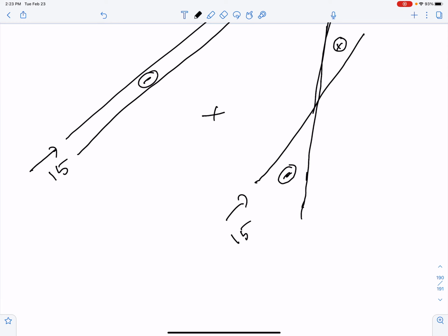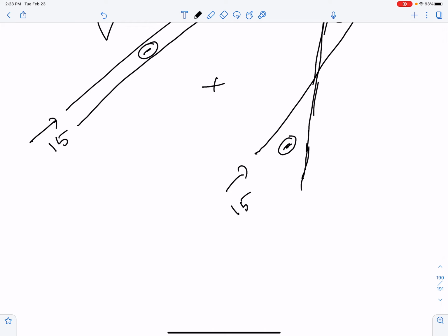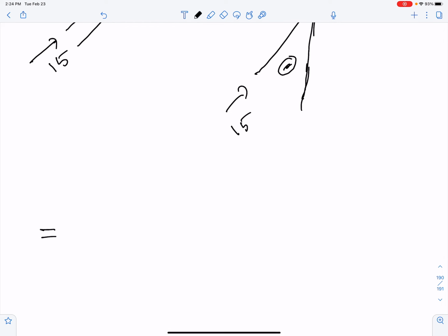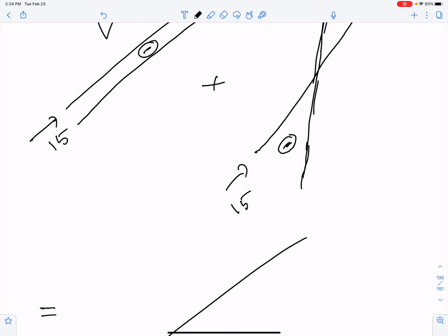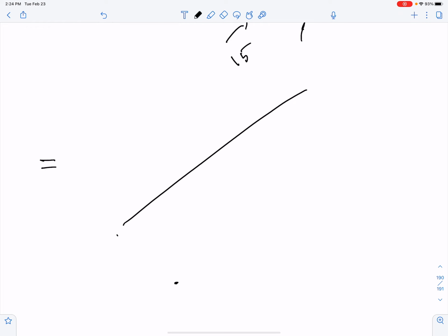And so now what you do is you combine the constant contribution, compression due to the motion of end nodes, with a linear contribution coming from the distributed force. Okay? And if you combine the two plots, you get something like this. Negative 15 and negative 15 combine to give you negative 30. Okay?